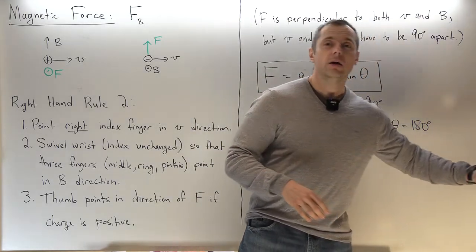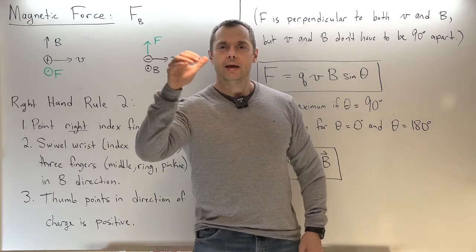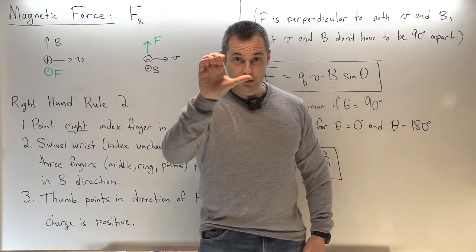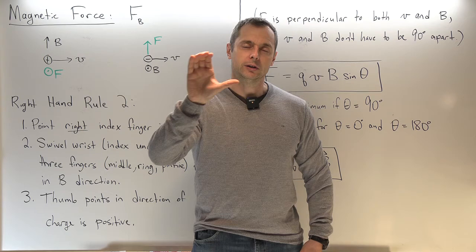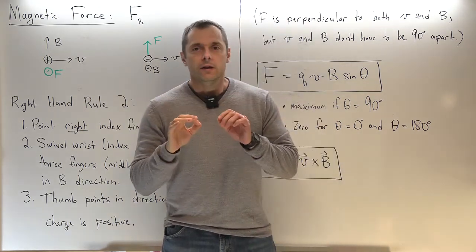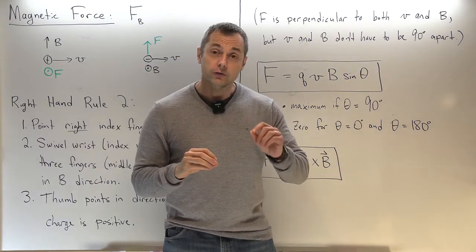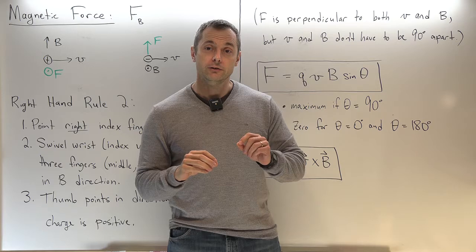So we needed a little tool to help us figure out the direction. The right-hand rule: you put your thumb in the direction of the current and your four fingers wrap around like this.